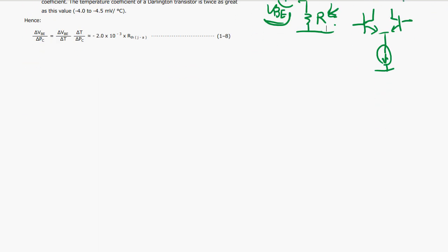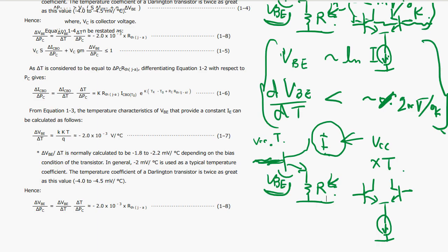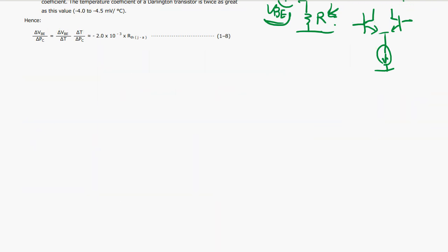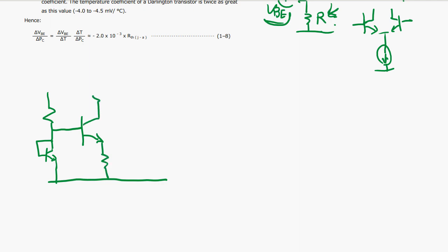So this is a very famous circuit to get a constant voltage. We use a transistor, the same as a diode, and you have another transistor and another transistor. We give negative feedback through this connection. This is called a bandgap.